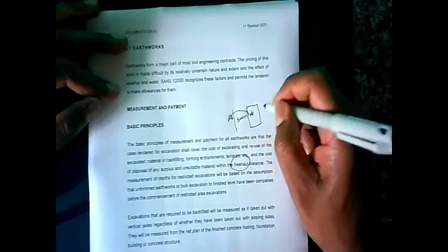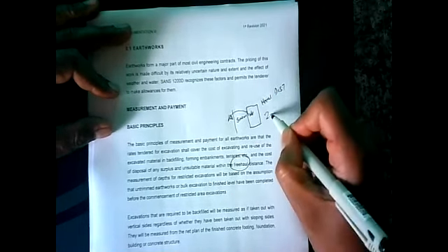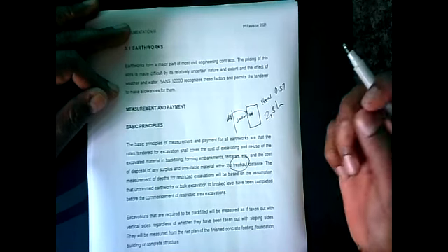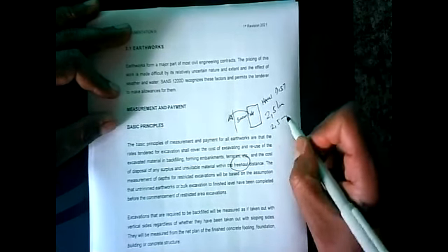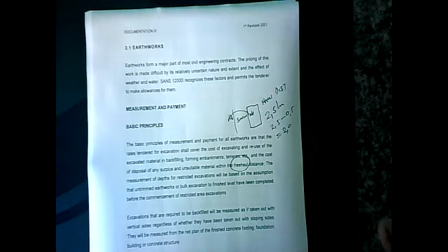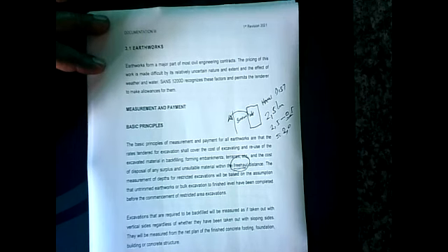So if we're saying that the whole distance of all this excavated material to dispose of is 2.5 kilometers, then how much in terms of distance will the client pay? 2.5 minus 0.5 kilometers, and he'll only pay for 2 kilometers of transport per load or whatever the arrangement is. All right, so that's what freehold distance is. The first 500 meters or half a kilometer, same thing, is free to the client.